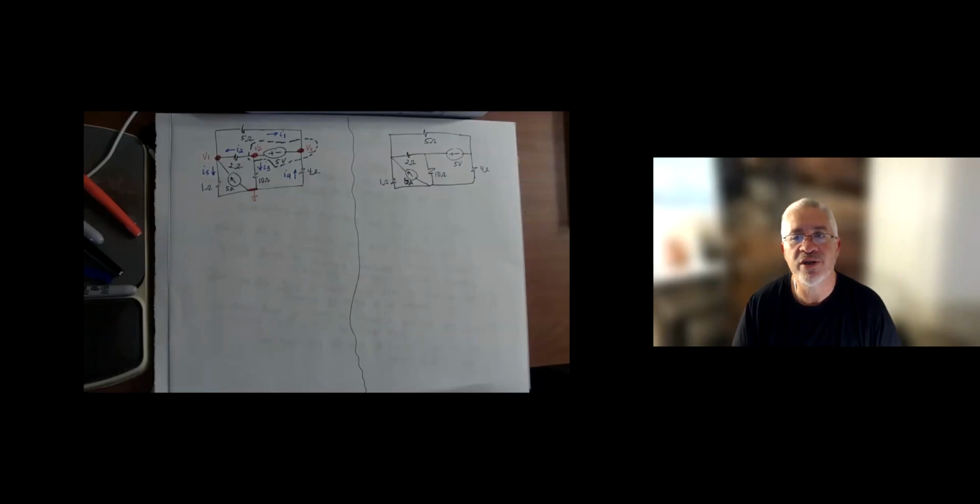One last thing that I'm going to do here, I'm going to ask how many voltage sources we have in this problem, and I'm hoping you answer me 1 voltage source. Okay, it is the 5 volt. Then I'm going to do a supernode around that voltage source here in green. So I have prepared the circuit for solution. You don't see my green too well, but you see my dashed line around the voltage source. That is my supernode. This is the case where the supernode does not have the reference node.